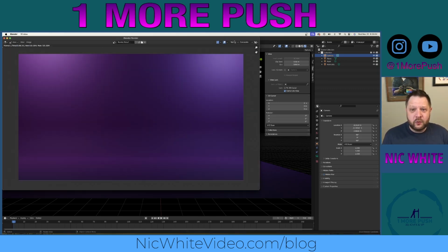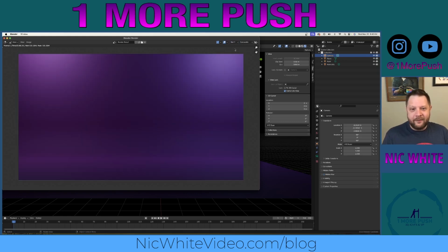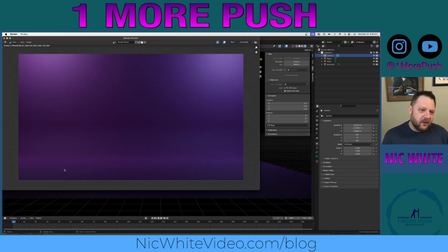There you go. And if we switch back to our first render, you can see what a difference that is. It's more than just an obvious color change and a slight highlight change, but in addition to that, there are some subtle gradients here and there, which can easily be adjusted if we add a third light or adjust the intensity of the two existing lights. But at the end of the day, I just wanted to show you how you can easily render out a cyc for use in your motion graphics projects using the free application Blender. And I hope that this has been useful for you.